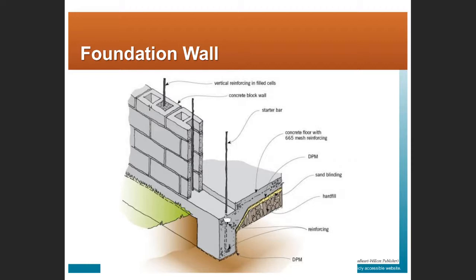You have rebar coming out of the footing, and as you stack the blocks up, you're extending that rebar up, and then you're filling in or grouting the cores of the concrete block. I think in the case of Delhi, the reinforcement was 4 feet on center. So some of the cores are going to be filled with concrete or grout, and some of the cores were filled with insulation, if I remember the detail correctly, right?